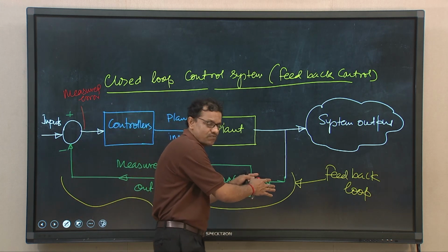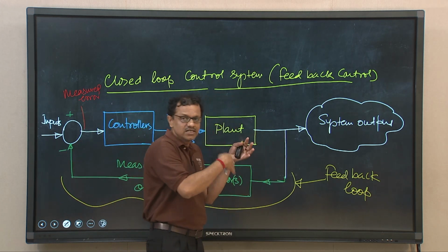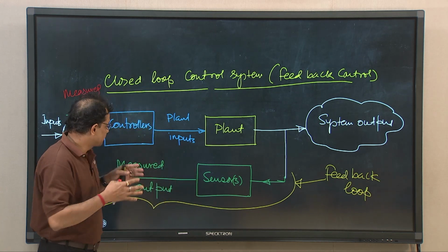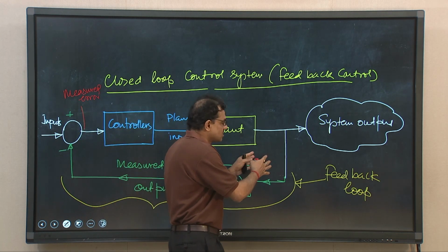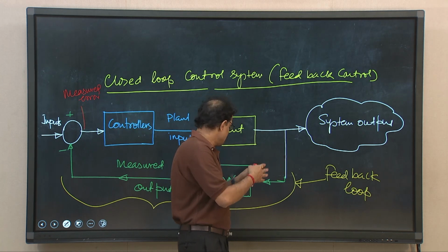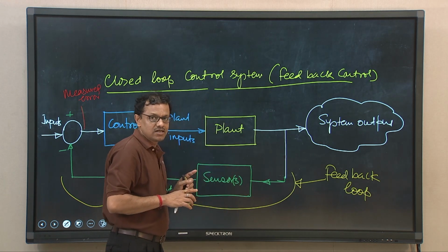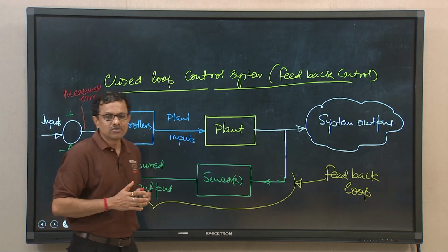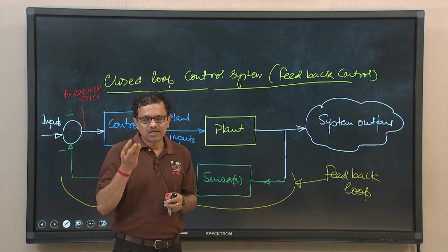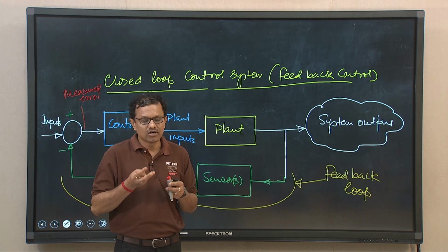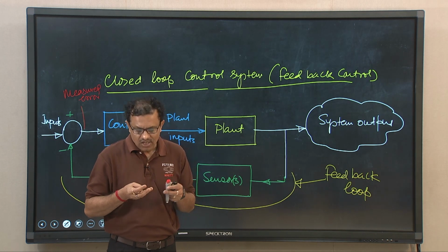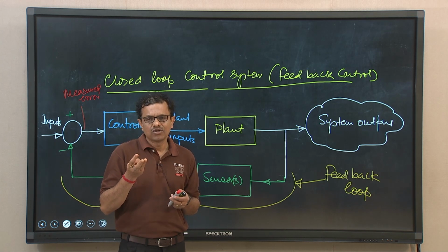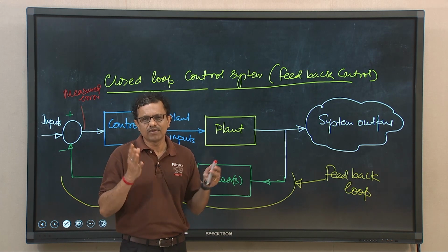This feedback loop allows the system to adjust for changing conditions by utilizing a few sensors that monitor the engine operating condition, like speed, throttle valve position, and coolant temperature. So engine operating condition means speed, coolant temperature, air temperature and throttle valve position.